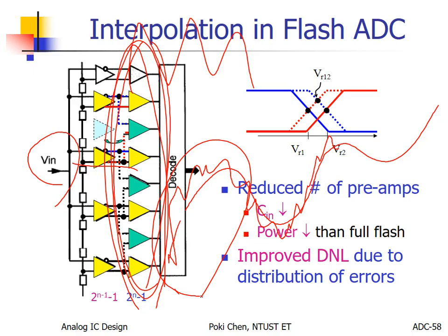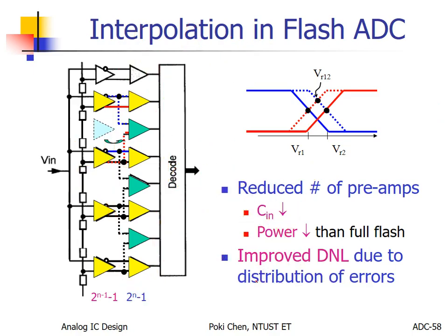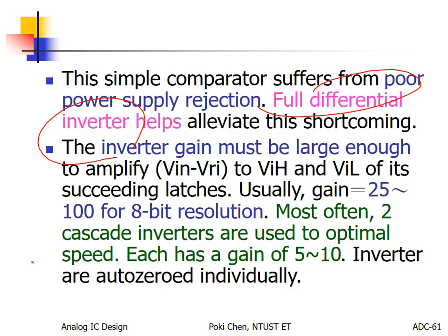It will hurt your effective number of bits for your final measurement. Even if your ADC works, you still need to face that kind of problem. So the fourth reason for a preamplifier is that it can help you to reduce the kickback signals. Again, from output to input, you get some kind of attenuation instead of gain.